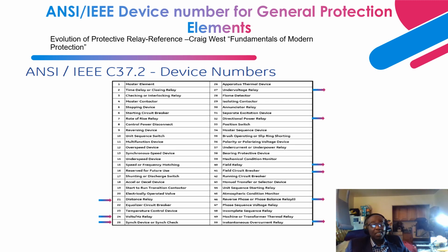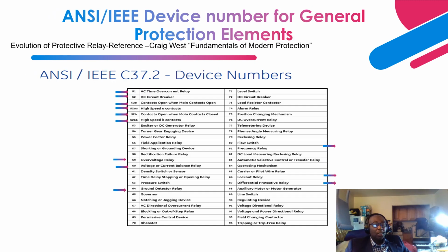Next is instantaneous overcurrent. This is usually a backup for the main differential protection, and is usually utilized in smaller generators, where there's no need to have a main protection scheme utilizing differential protection. Next is time overcurrent relay, ANSI device 51. This has much more timing. It's not instantaneous and operates on an inverse current. It protects the generator based on overloading and onset of fault.